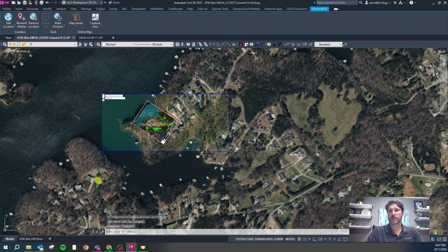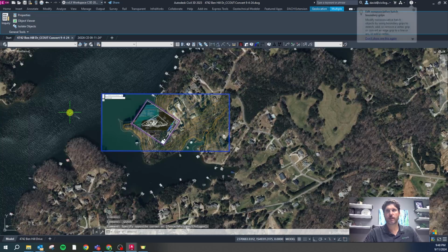And then, because that deletes any unreferenced items that may be in the drawing of objects that don't exist, we're going to run audit, fix, yes. And it's probably going to find some errors. And then save. It's probably a good idea to save before and after. Okay, let's try this again.